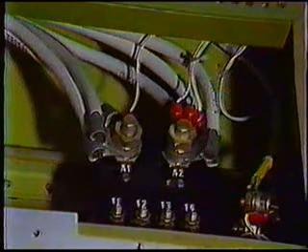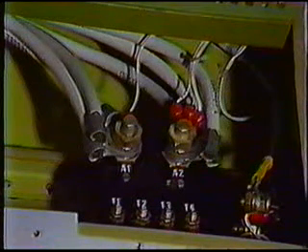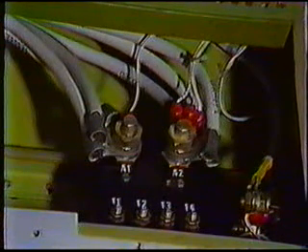Several relays are used in the generator system. The largest of these is the generator relay itself, referred to as the main contactor. It is installed on the right-hand side of each nacelle. This is the primary means of connecting and disconnecting the generator to the aircraft wiring system. Control of this relay is shared. When the pilot moves the respective generator switch to the on position, he is signaling for the relay to close. But the generator control unit can either not allow the relay to close or open it at any time after it closes, if the control unit senses any abnormal function or condition.